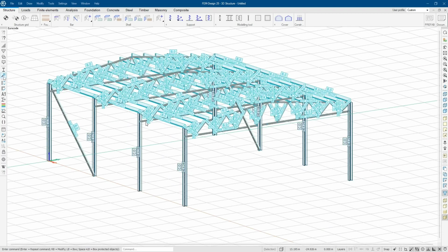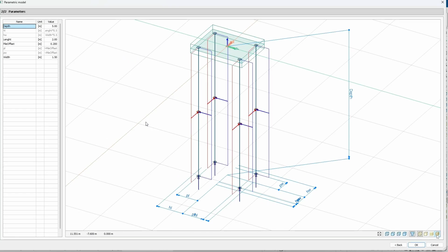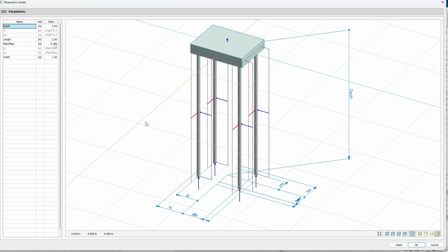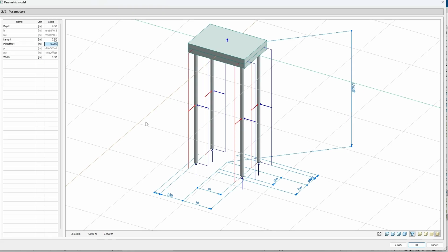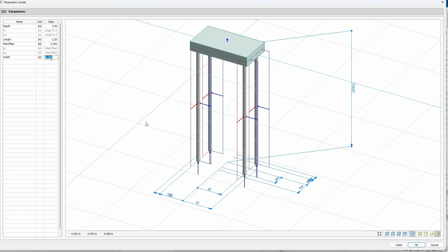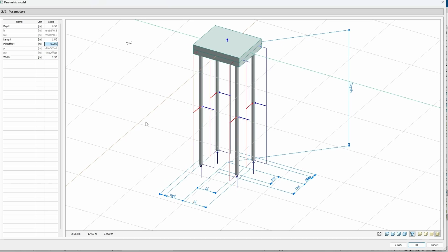And there it is, and then we might want to use our piling cap model, what we just made, like this one. And then we can give it some parameters. By the way, if you use those lateral springs, they have to be divided in the height direction, because the soil properties and the capacity in lateral direction are a function of the depth and the density of the piles and many things. So now this is a too simplistic model, but it gives you an idea how it works.